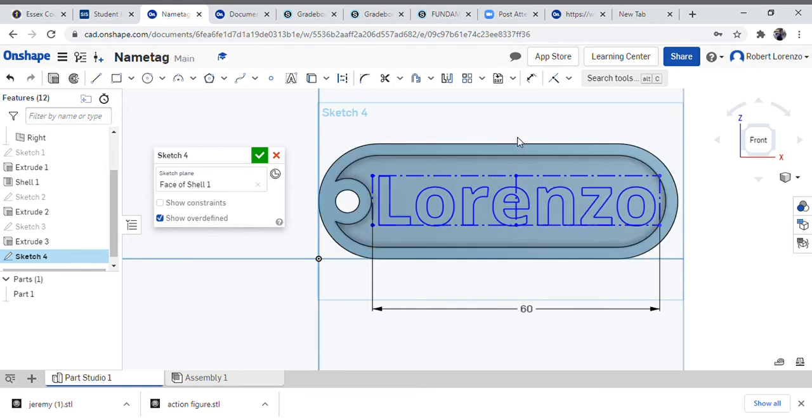If I want to center it top to bottom, I'm going to show you a quick cheat here. You guys can do it or not. So I'm going to start a line here, drop it down. Sorry, I'm in dimension. Line, I'm going to start a line, right? So I chose line. Make a line, drop it down. Press escape. I'm going to make another line. Start here, bring it up. And then hit escape again.